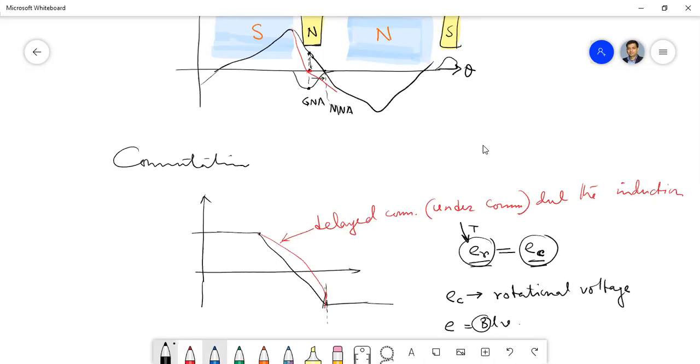Okay, so from the experience or from the analysis, we have seen that if we have some negative flux there, instead of having this exact cancellation of the flux present due to the armature reaction at the interpolar region, if we have a slightly negative flux there, so if the contribution of interpole is like this, what will be the resultant mmf in this?